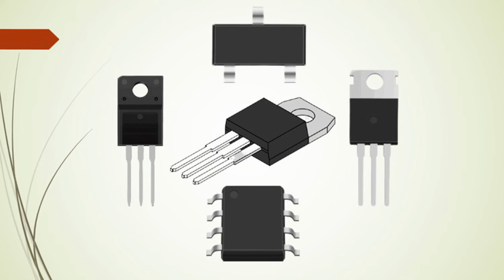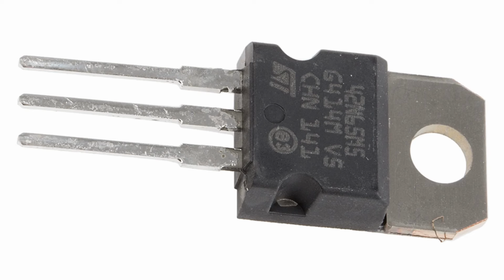Summary of operation. In summary, a power MOSFET operates as a voltage-controlled switch, enabling or disabling the flow of current between the drain and source based on the gate voltage. Its efficient switching capabilities and low on-resistance make it ideal for various applications, including power management, motor control, and signal amplification. The key operating parameters, such as threshold voltage, on-resistance, and switching times, are critical for ensuring optimal performance in practical applications. Power MOSFETs exhibit several key properties that make them suitable for high-power and high-frequency applications.